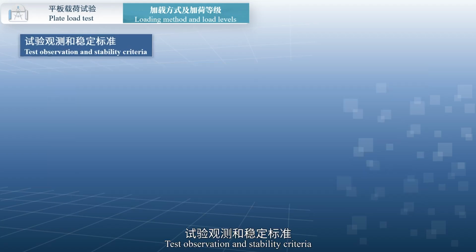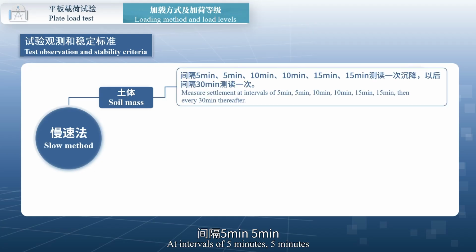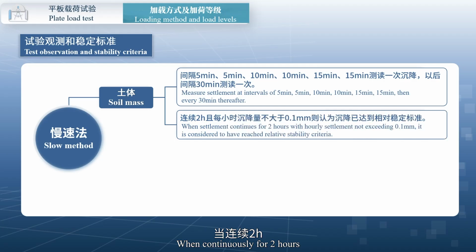2. Test observation and stability criteria. Slow method. For soil, after each loading grade is applied, at intervals of 5 minutes, 5 minutes, 10 minutes, 10 minutes, 15 minutes, 15 minutes, measure settlement once, thereafter at 30-minute intervals measure settlement once. When, continuously for 2 hours, the hourly settlement does not exceed 0.1 mm, then the settlement is considered to have reached the relative stability criterion.